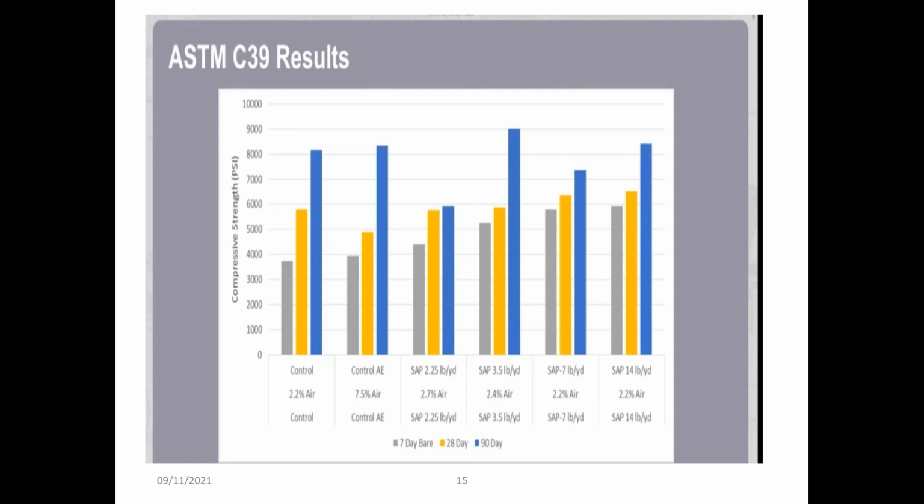Towards the left, we can see the first specimen, on which the test was conducted in a control environment with only air entrainment of about 2.2% of the whole volume of the specimen. Now, this specimen shows the most valuable result, and it can be used as a reference concrete. So, using it as a reference specimen, we will compare all the other specimens. Here we can see as air was increased in the second specimen, it shows basically no change or variation in the 90 days strength.